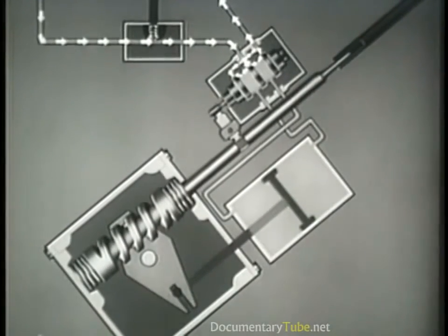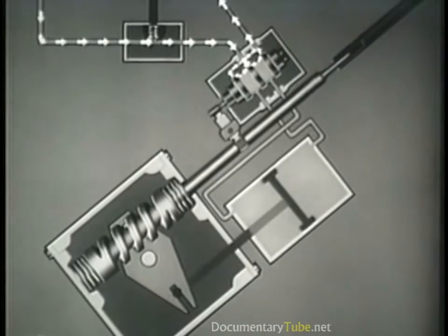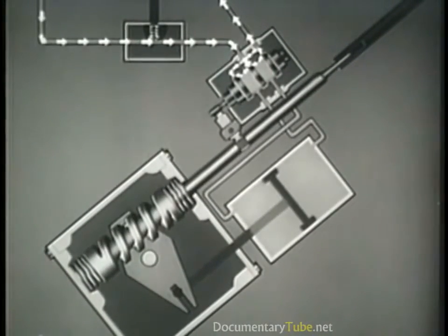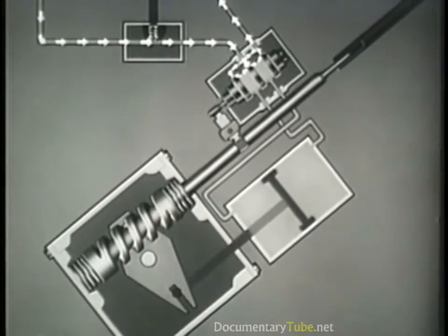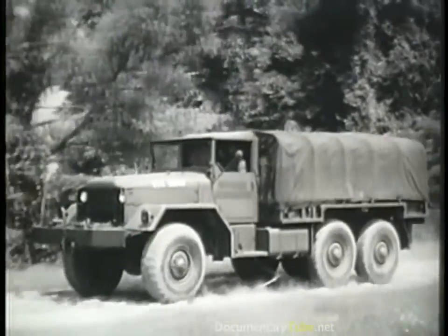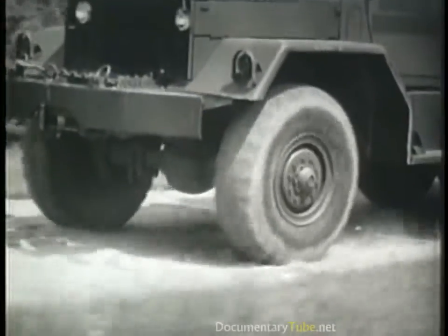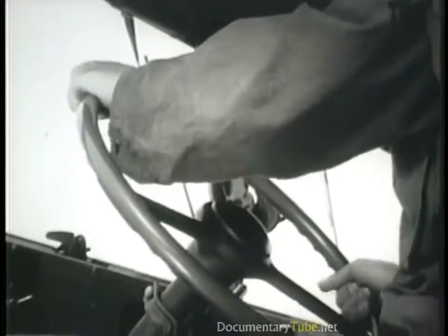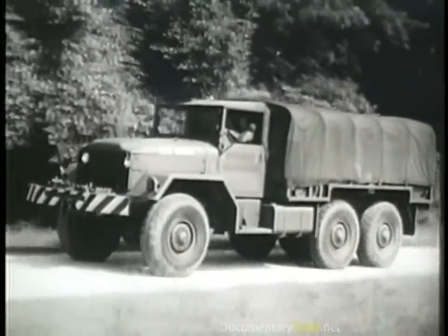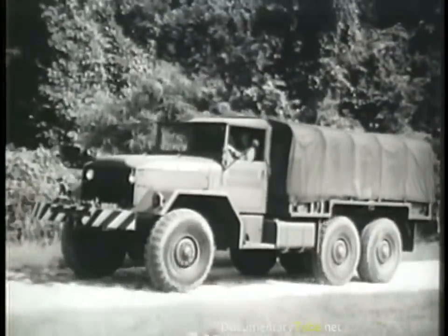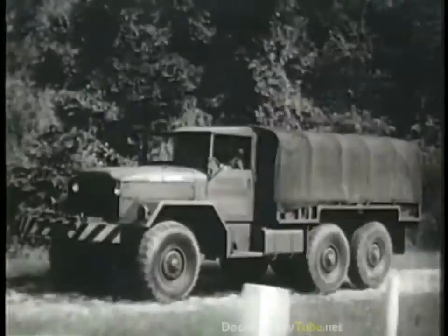On return to neutral, all fluid from the pump is directed back to the reservoir. The pressure is lowered throughout the hydraulic system, and the piston and piston rod do not function. One of the steering problems of the heavy vehicle with cam and lever steering is road shock. Road shock causes kickback of the steering wheel and makes control of the vehicle difficult. On the other hand, heavy military vehicles equipped with hydraulic steering resist road shock through a reverse action in the power cylinder.